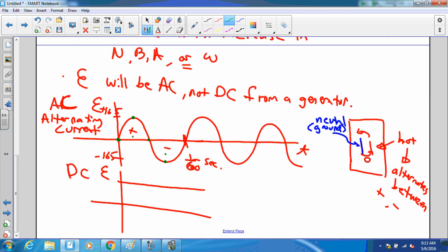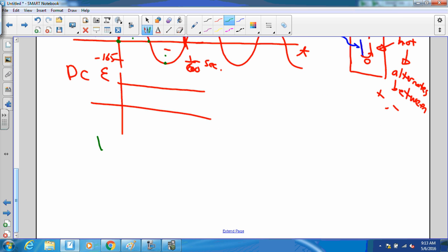And so the average power is proportional to the square of the voltage. And it turns out that when you have a sine wave or a cosine wave, and you do a little bit of calculus with it, then the average of the square of that sine wave or cosine wave, the average value of cosine squared, the integral of, blah, blah, blah, then what you get is the maximum divided by root 2. This is called the RMS, or root mean square average.